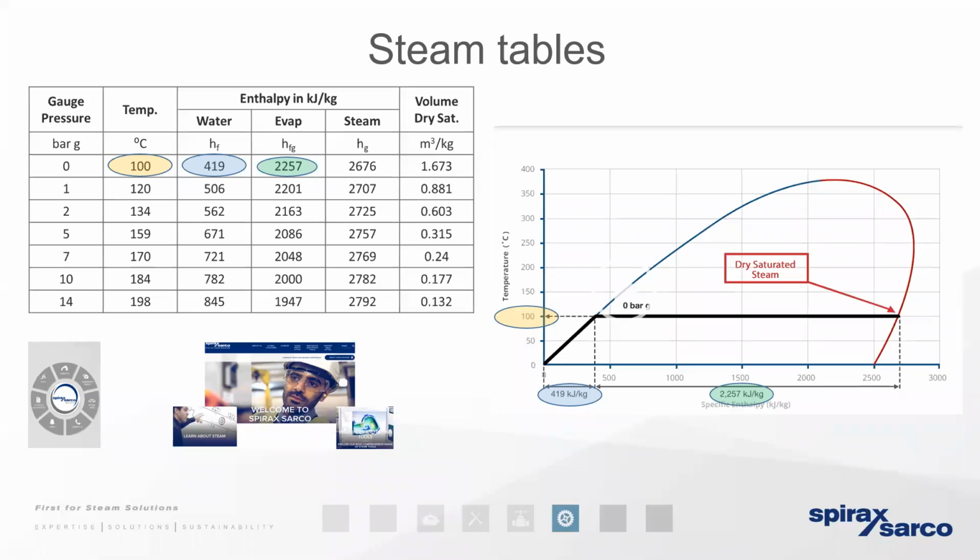So it's important to understand that when steam gives up its heat energy, it does so by condensing. It changes state from a gas back to a liquid again. And when steam condenses, it gives up its enthalpy of evaporation. In other words, it's that latent heat energy. It's the energy that we added to the boiling water to make it evaporate. That's the heat energy that can be used by the process, that's demonstrated in that middle column with the little green oval. That's the useful heat energy.